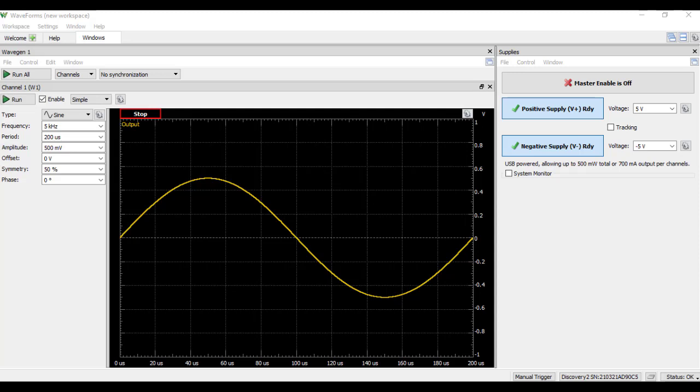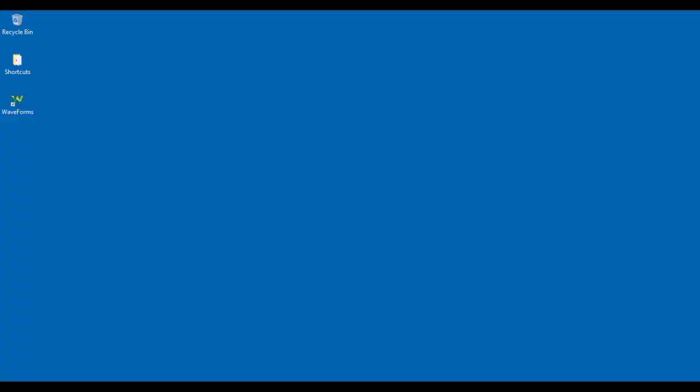Now keep in mind that although you haven't actually built a local oscillator as part of your Superheterodyne receiver, this application, EECS AM Superheterodyne app, will automatically use the local oscillator that's inside the 82. And the application's user interface will allow you to turn a knob which corresponds to changing the local oscillator frequency. So close out of the Waveforms app.